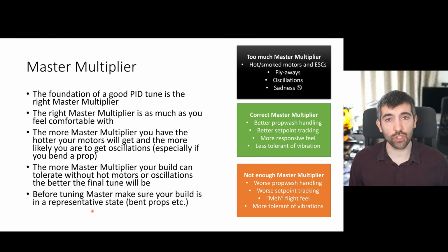So before tuning, make sure that your build is in a representative state. So if you commonly fly with a GoPro, make sure the GoPro's on there. And if you usually fly with slightly damaged, nicked or bent props, make sure that those are the props you're using for the tune. And that will make sure that you get your master multiplier as high as you can without risking any hot motors or oscillations while you're actually flying.